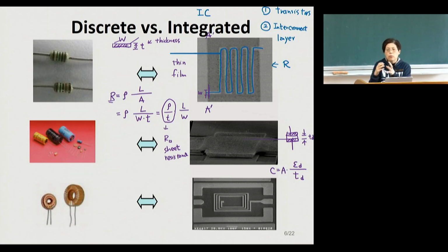The reason why, even though in an integrated circuit we have the capability of making integrated inductors and capacitors, mostly they are not very ideal, meaning that it would take a lot of area to make some substantially large capacitors. And also, capacitors are a very expensive thing because they take up a lot of area.